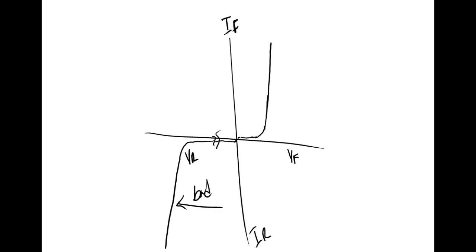So we'll come in here, we'll hook up about 5 power supplies, we'll pump that thing up, and we'll look across that resistor, and we'll notice when current shoots up and it breaks over. And then we'll get a soldering iron and we'll put it up next to it and we'll see the current goes up. And we'll get the freeze spray and we'll spray it and see the current drop down. So you'll actually see that reverse current vary with temperature. The VF side, we'll do that as well.